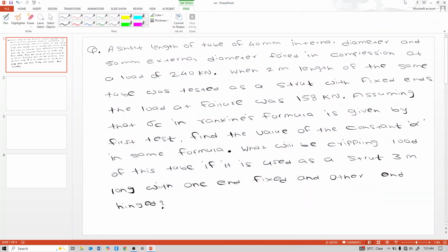Today, in this video lecture, we will see this fourth numerical on Rankine's formula. So, first see this numerical. A short length of tube of 40 mm internal diameter and 50 mm external diameter failed in compression at a load of 240 kN.